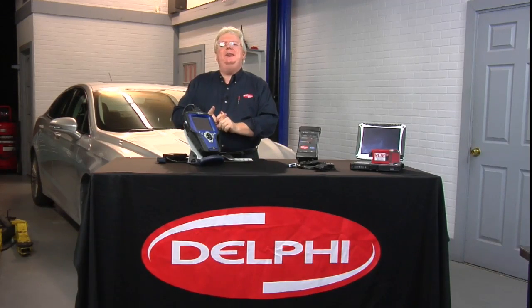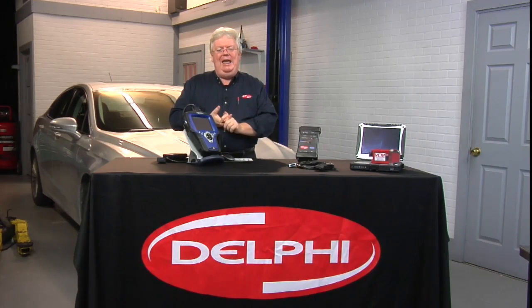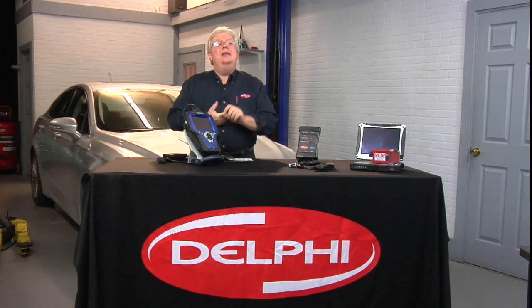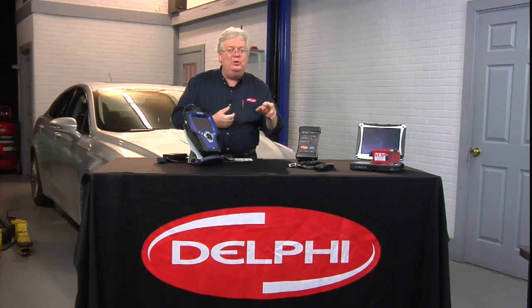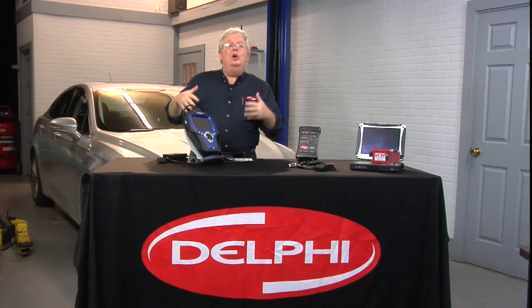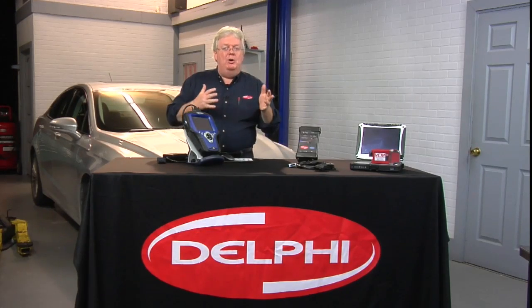Chrysler DRB3, DRB2, on the other hand, never had mode 6, and GM Tech 2 did not either, so the majority of the older factory scanners that you're more used to, if you're a tech not working on the latest new cars, did not have mode 6.